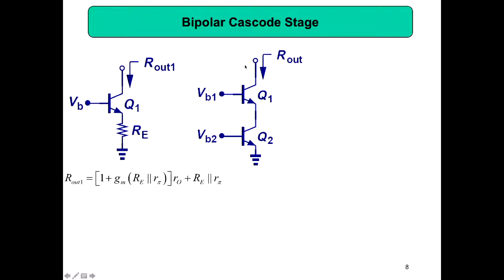Why are we using two? Because if you are using only one transistor, your output impedance is very small. That will make your current source very real, not ideal, meaning with less output impedance. But if you connect another transistor here, then you are boosting your output impedance so that you can push your current source to the ideal characteristics, very high output impedance. And then we know that when we connect a transistor here instead of Re, what will come into effect here?